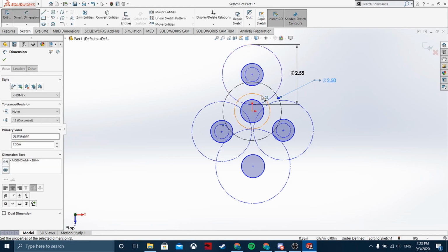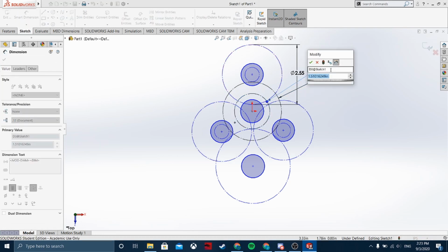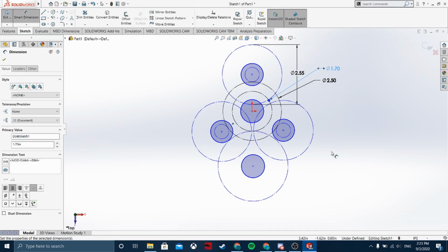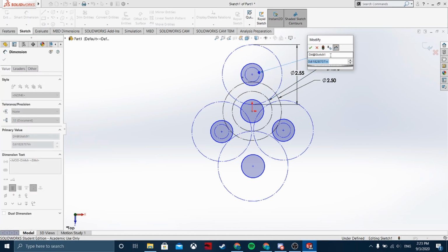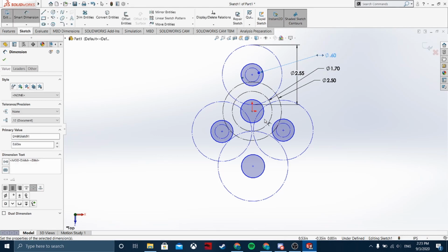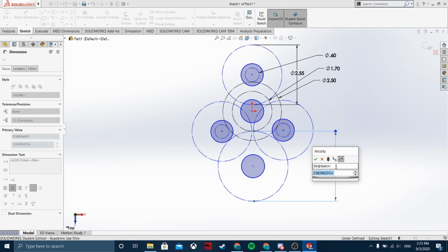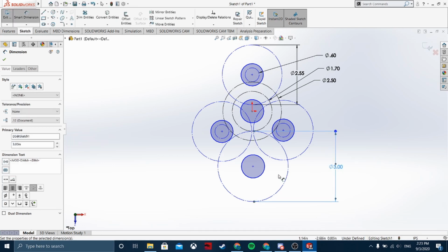So we can calculate 34. If you just type in 34 divided by 20, SOLIDWORKS automatically calculates it for you. If you press enter, 1.7. The pinions are 12 tooth, so 12 divided by 20, 0.6. The 60 tooth gear is going to be 3, because 60 over 20 is 3.